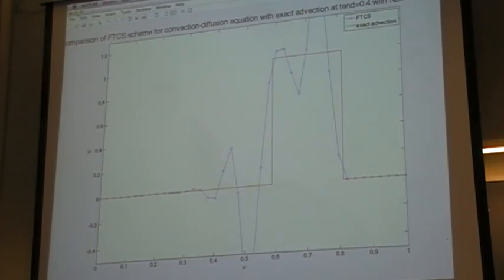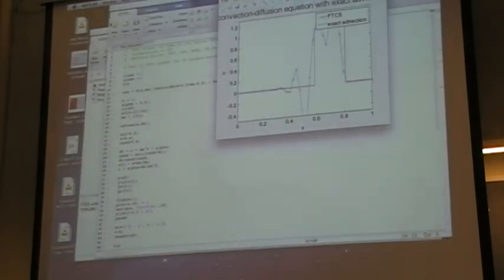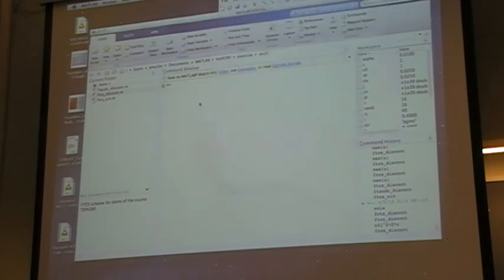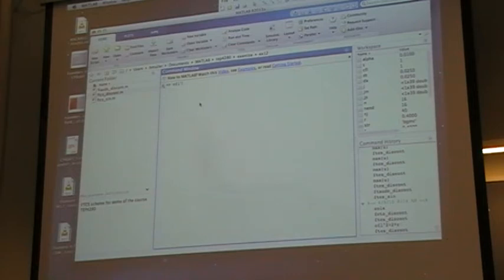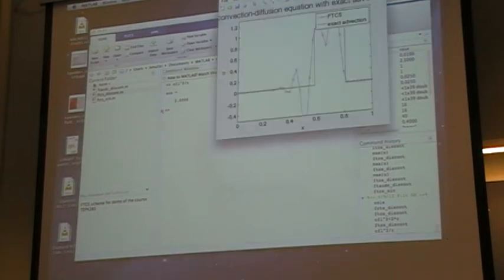Let's see, we can check that the following way. We can look at the CFL number. That is my acronym here for the Courant number. That is to the power 2 divided by the von Neumann number. You see it is 2.5. It should at most be, for being stable, 2. So this condition is violated, and the result of that is that we get an instability.